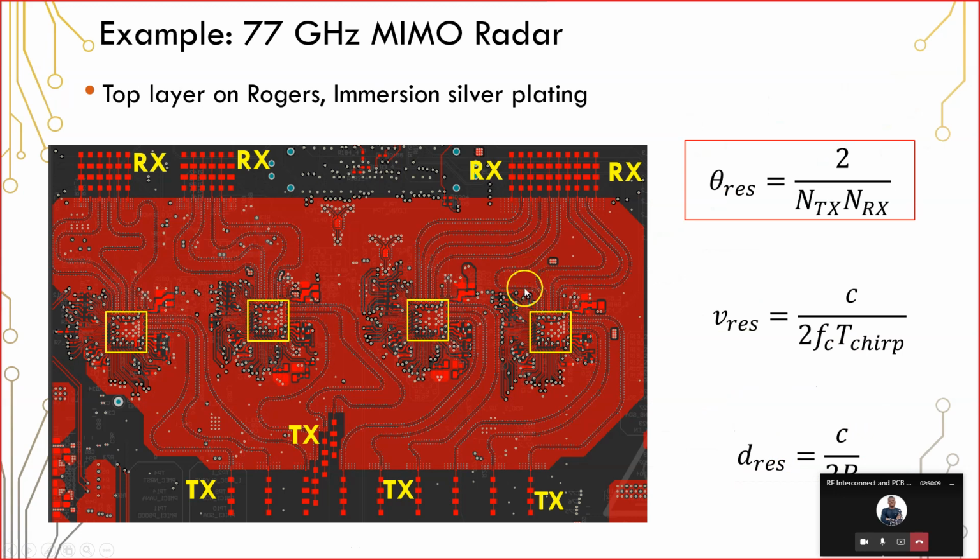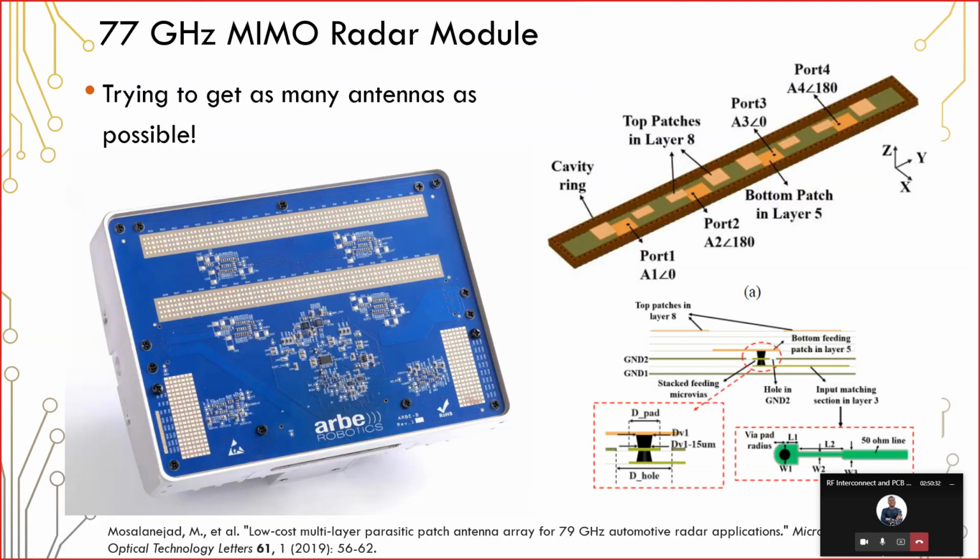Another example is actually in this design because all of these chips have to be synchronized so that you can define a definite phase difference between each of the signals sent to the antennas. And so that requires a low frequency oscillator on an internal layer. So on L3, there's a low frequency oscillator that then has to pass through vias in order to reach each of these chips. So in some cases, you absolutely must use vias.